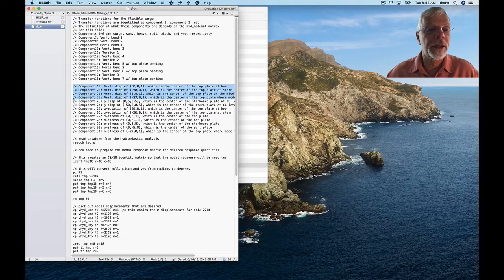And so I haven't formed that psi part yet, so I need to do that. I need to go in and extract the nodal displacements in each mode out of the matrices to get those values. That's actually through component 19 through 26, because I'm getting the vertical displacements, some y displacements, and x rotations.